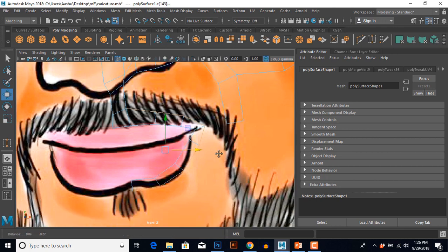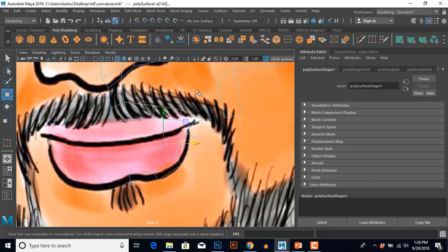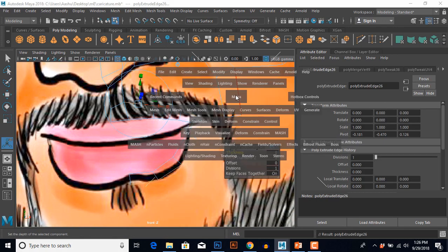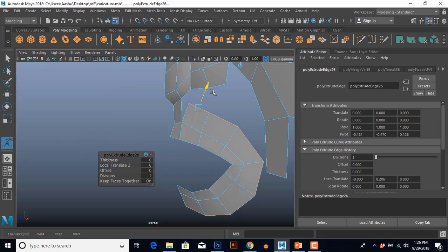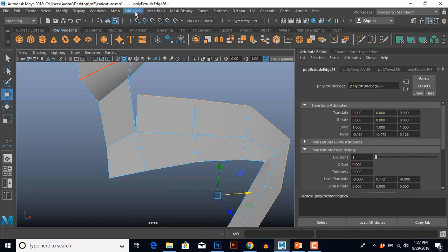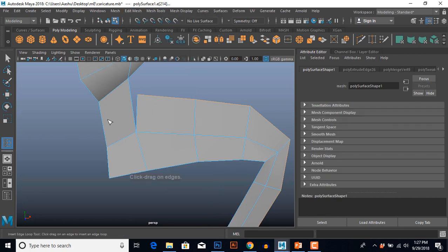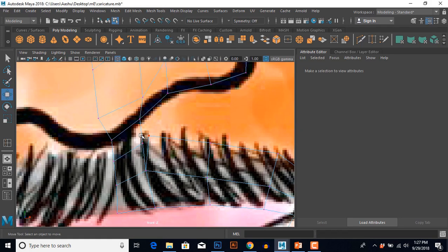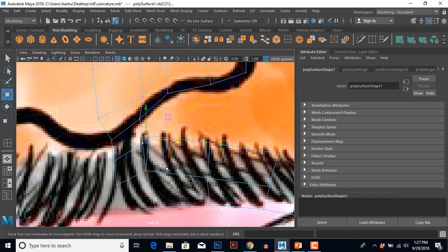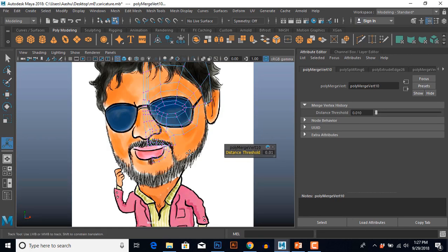Going to complete this area, so go to edge mode, select all these edges here from front view and shift right click, extrude edge, and from perspective view extrude them outside. We don't have a side reference, so we all need to do according to the right observation. So it is recommended to do the work carefully while you do these kinds of works.